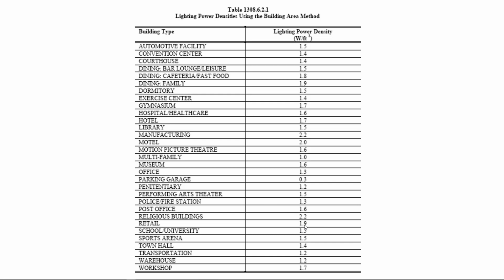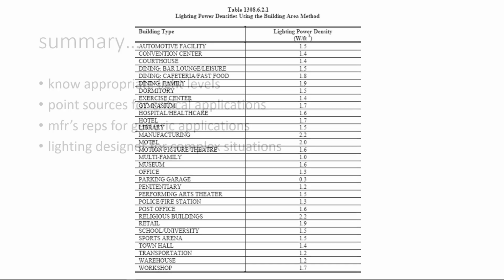It does not have anything to do with the quality of the lighting. However, the higher the lighting power density you have, it stands to reason that you're going to have a much higher electric bill because you're using more power per square foot. In a retail setting, that's probably fine. In things like schools, they're often shooting for a lower power density than the maximum allowed by code, just because these numbers are actually not particularly aggressive or sustainable.